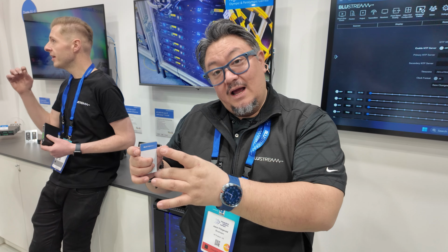So really, because we have a transmitter and a receiver, we can do all sorts of scenarios. A great use case for the IP350 is that I've got my receiver, it's taking video from any one of my sources, and at the receiver, I take the audio from there and put it into Dante. Now, what does that give you? That gives you switched audio now into your Dante system, all right?